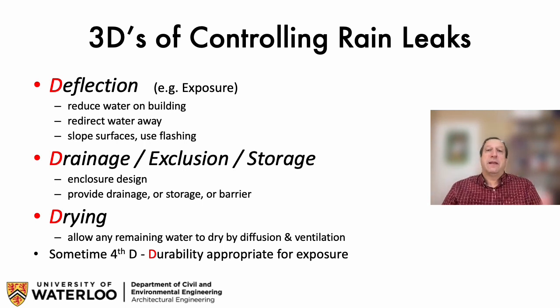And then finally, there's the drying side. As I'd mentioned, we can tolerate a small amount of built-in moisture, a small amount of condensation, and a small amount of rain leakage because materials can store moisture and then they can dry it out. And if they dry it out soon enough, no problem. And so consideration of drying becomes important. And that's the third D of the 3Ds.